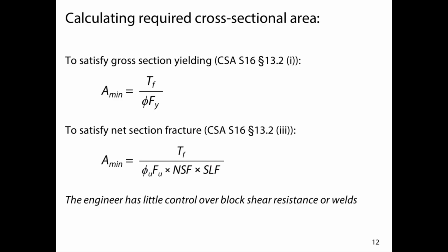And I'm going to throw my hands up when it comes to the welds or block shear, because I have very little or no control over block shear and weld resistance calculations. That all sits with the fabricator. And even if we're doing a welded connection, we may still want to use the bolted values for NSF and SLF here for doing that kind of thing.